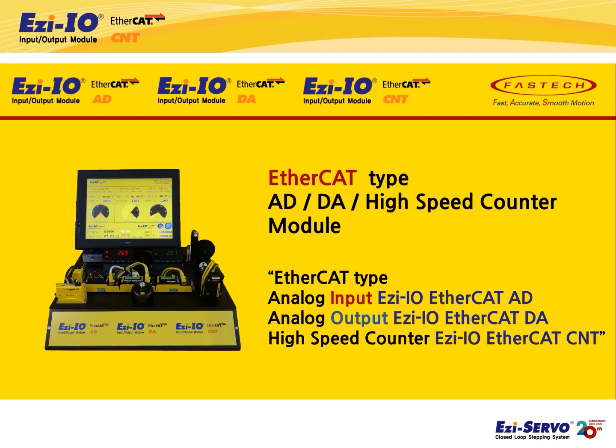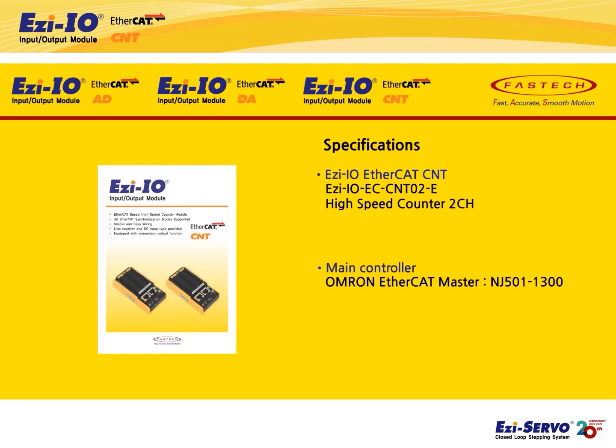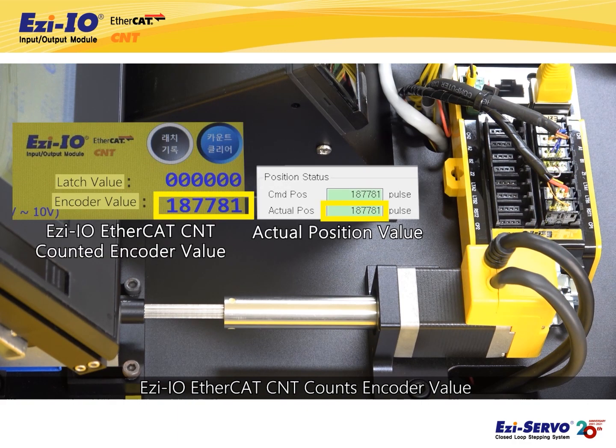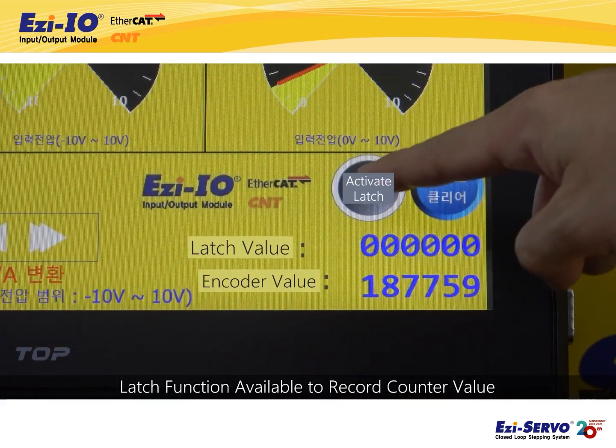Lastly, I will show you the demonstration video of high-speed counter module using EtherCAT network. The product names used in this demonstration are as follows. Ezi-IO EtherCAT CNT counts the encoder value and displays the value on the HMI. You can see that the counted encoder value and the actual position value of the motor from the drive match. Also, you can check the latch function mentioned earlier.